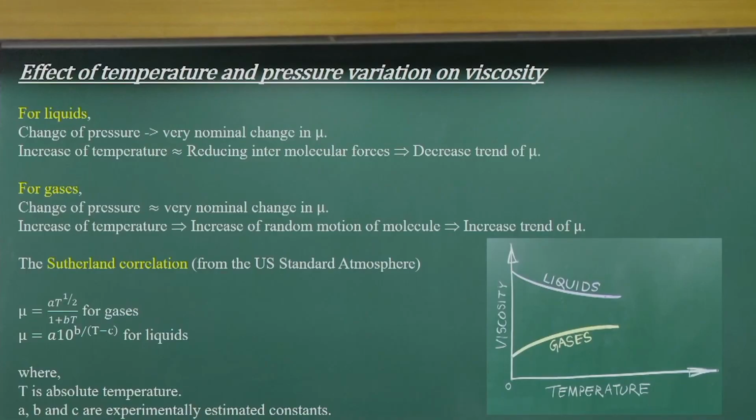Now let us look at how temperature affects the coefficient of viscosity. For this we have to look at the molecular level. When you talk about liquids, they have molecular bonding forces between two molecules, but these are much weaker when you talk about gases. So gas molecules have more random motion as compared to liquids.